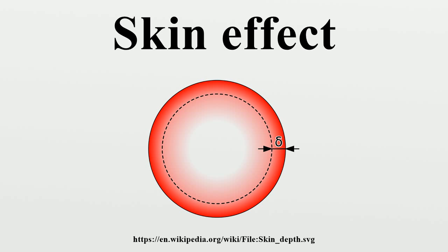At low frequencies, all 3 inductances are fully present, whereas at high frequencies, only the dielectric region has magnetic flux, so most discussions of coaxial transmission lines assume they will be used for radio frequencies, and equations are supplied corresponding only to the latter case.